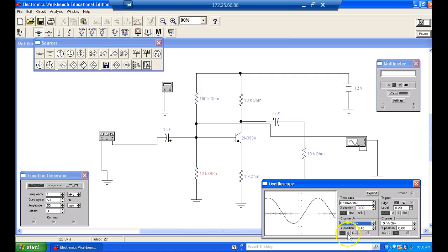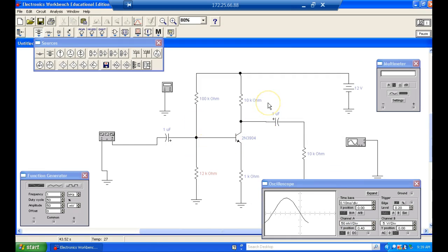So if this guy right here opens, the transistor does what? Saturates. If this guy right here opens, the transistor cuts off. Are we okay? Okay. Every time. But you can tell by the bias. So over here, if we know this voltage right here, we expected 6 volts over here, and this guy had dropped down to 1.2 volts. So we know the transistor had moved toward what? Way toward saturation. Right? Okay, so what should happen if this guy right here opens?